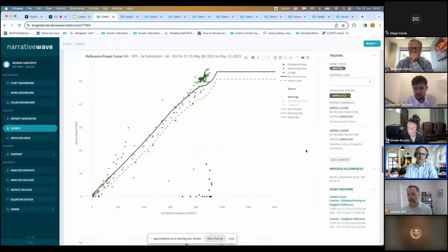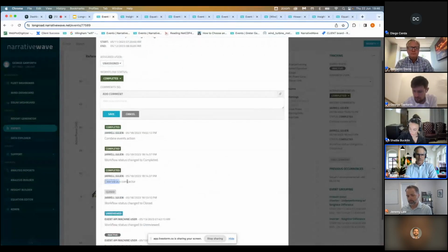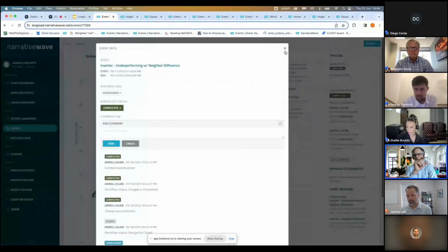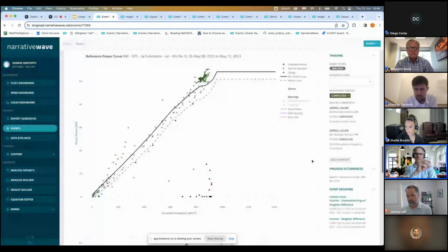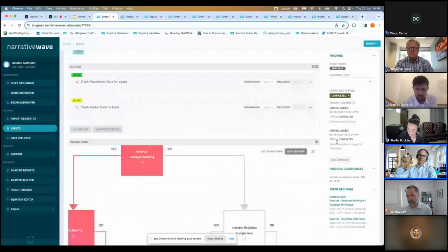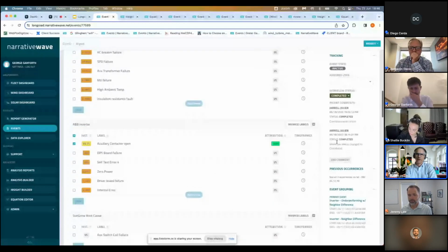In this particular case, the AC contactor is a contact that closes the main power contact when irradiance or voltage is high enough. If that irradiance is low, or there's degradation on the panels, which there is, or there are DC string issues, which there are at a 12-year-old site, that contactor will sit there and chatter intermittently. Across the 180 inverters, if there's two or three, it's fairly easy to see. It's hard to manage, right? Because we have a lot of data coming in, comm issues and whatnot.